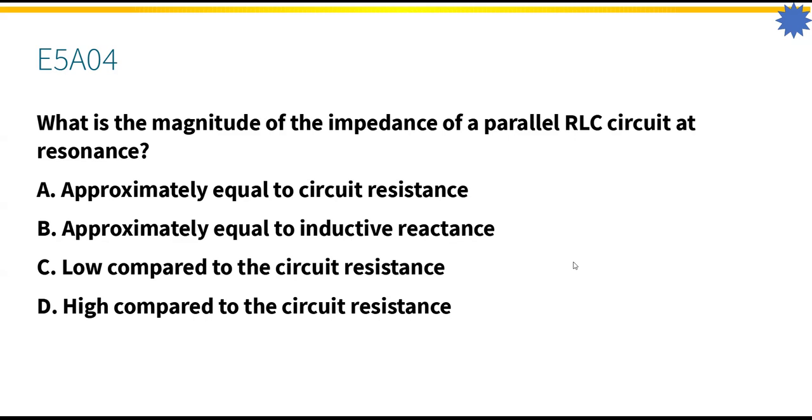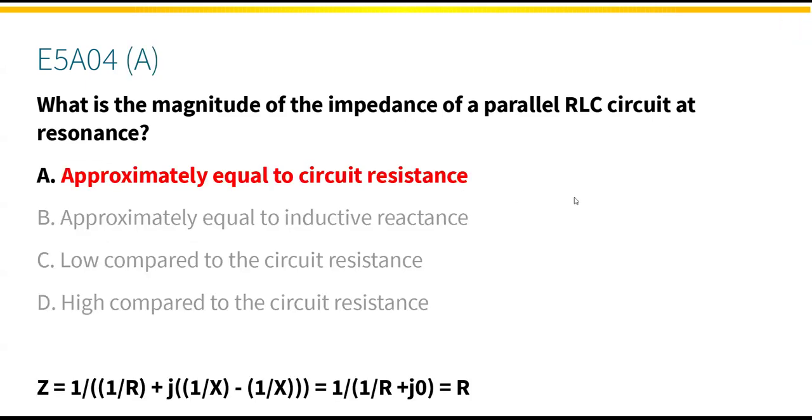We've got two impedances in parallel. One's high, one's what, 1 ohm? Or whatever it was, the resistance. So it's going to be equal to the resistor. If you didn't have a parallel resistor, then it would be on its way to infinity. And down there's how you figure that out. How do you do it? Well, it's the reciprocal of the sum of the reciprocals.